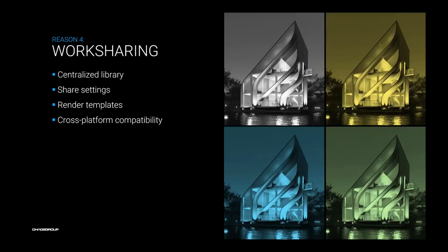Why it doesn't work like this? Because every team member might use different V-Ray settings, and syncing to Central might override other team members' settings. Therefore, the V-Ray settings are stored locally and they can be shared easily in case a proper workflow is established.